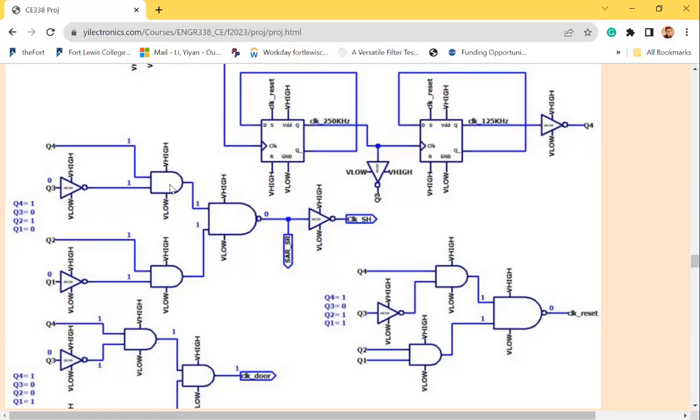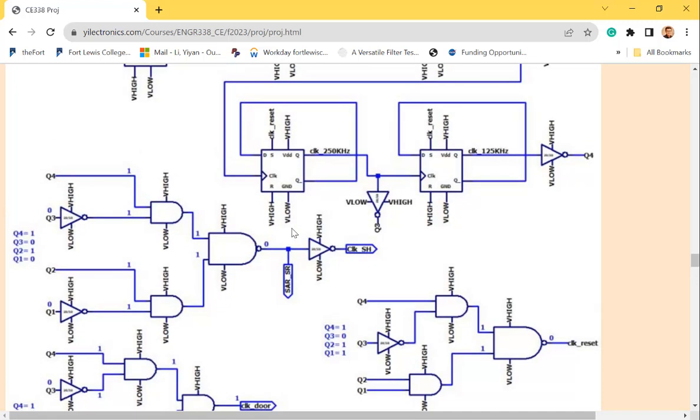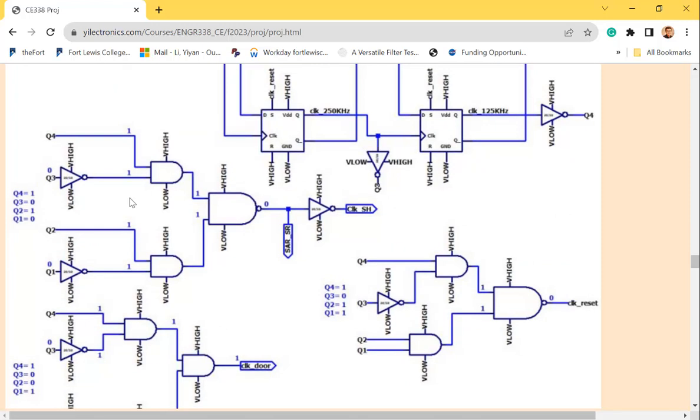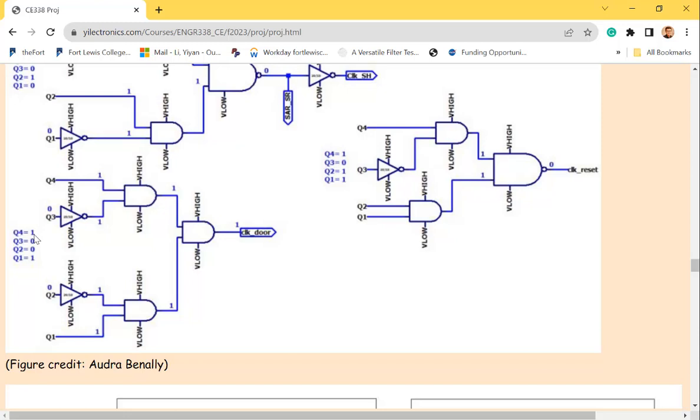There are some modifications because some of the circuits are zero active, so I have to modify some of the gates really quick. But you can see a NAND gate with an inverter, it's just an AND gate. You combine these two together, it's just an AND gate. I split it so I can get a 0 in here for some zero active D flip-flops. So in this example, I'm counting to 10, and this one counts to 9.